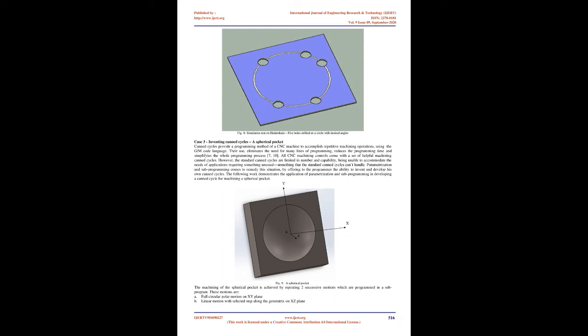Case studies. Complex motions, Serpentine curve. The case of a serpentine curve, figure 2, was selected to illustrate the mechanism of generating complex motion using subprogramming and parametrization. Figure 3 shows the flowchart at which the program of list 1 was based on. The same program can be executed to machine a serpentine of any size, at any starting angle, with any angle step and any milling depth. Simulation results are shown in figures 4 and 5.